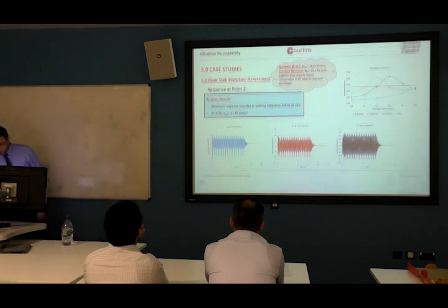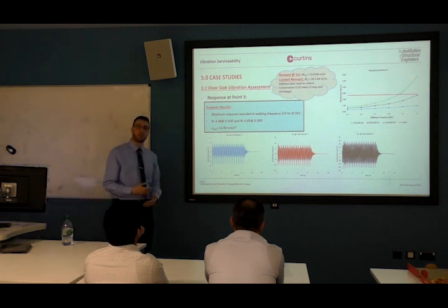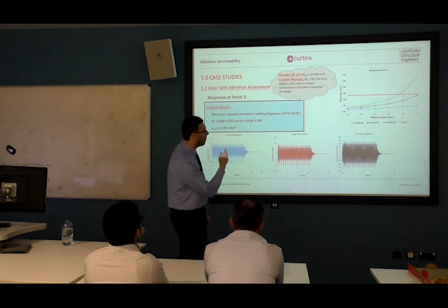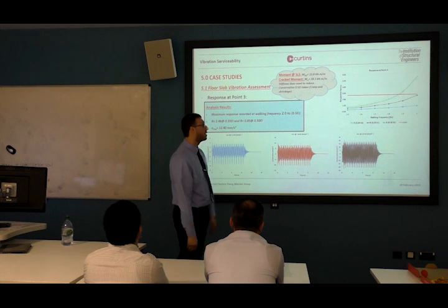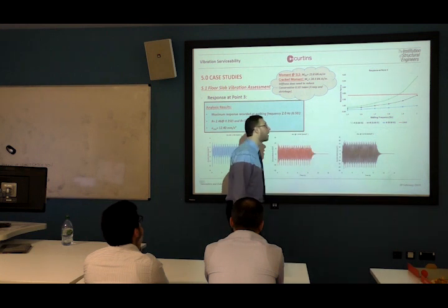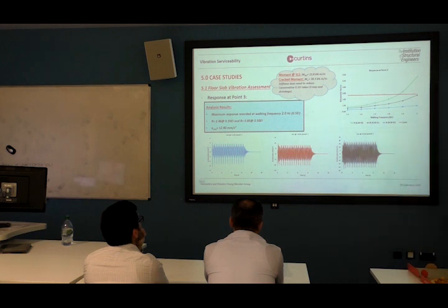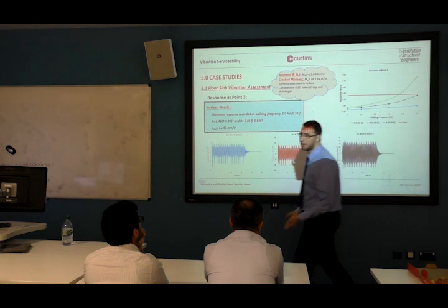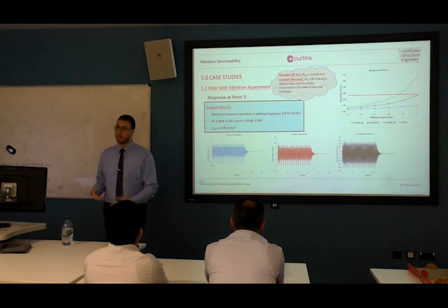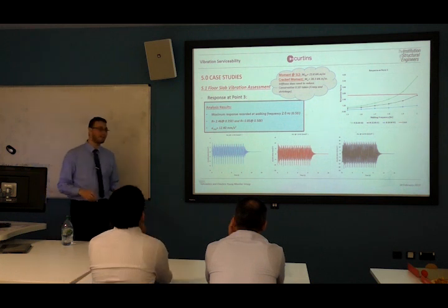And we repeated the same for 0.3 and checked how much cracked section we had, and checked also how much response we're getting at maximum walking of 2 hertz. Now remember, if I am checking at 2.1 and 2.5, I would expect this curve here to go something like that. But this is walking in the flat itself. So I am limited to 2 here, which is fine. So you have something to put in your back pocket and check. Okay, it's all right.